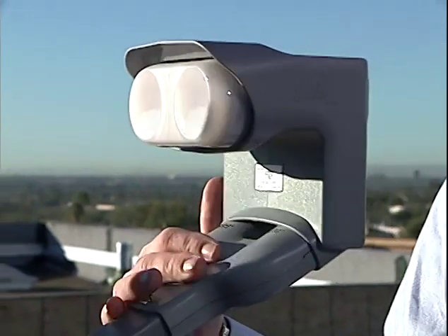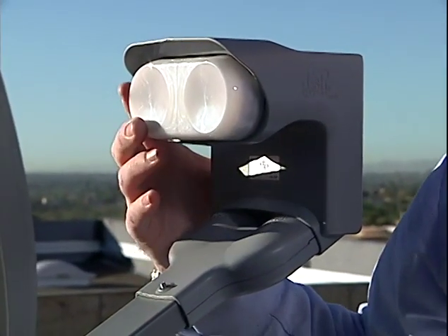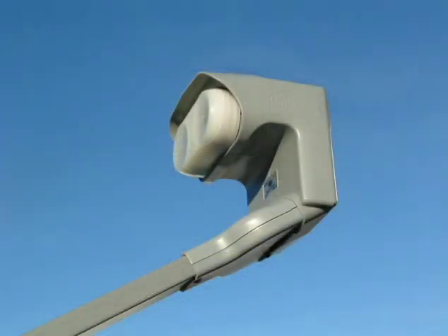Newer Dish Pro antennas for the Dish Network have 2 LNBs to receive the network's primary signals at 110 and 119 degrees. The LNBs and receivers operate differently than the ones we saw for DirecTV. They incorporate a European standard called Digital Satellite Equipment Control Protocol, or DiSEqC for short. It allows two-way signaling between the LNBs and the receivers.